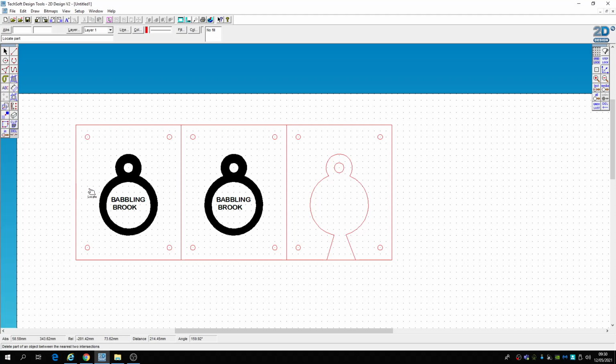The only other thing we're going to do is we've joined 3 squares together, and if you don't want your laser cutting multiple lines, if you just click on that once, that gets rid of it. But just to prove it, if I click that, it disappears altogether. So we go back to undo last, there we go, and that puts one line back in. What it means is it won't go over it twice. And we click that once and get rid of that.